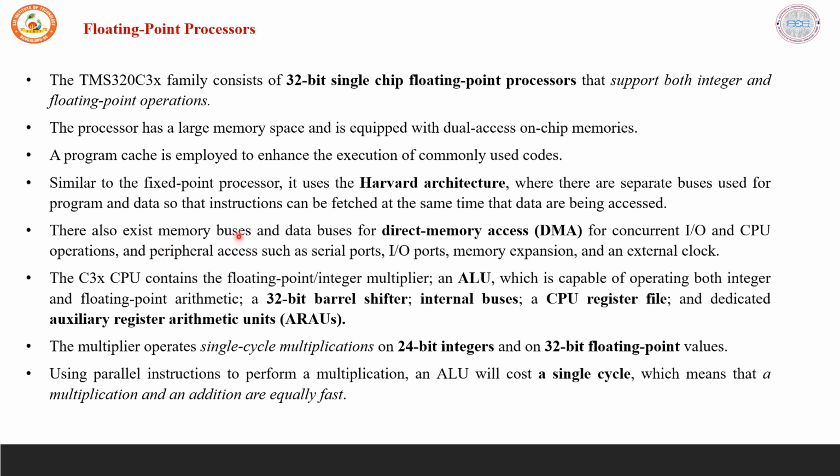There also exist memory buses and data buses for direct memory access, for concurrent I/O and CPU operations, and peripheral access such as serial ports, I/O ports, memory expansion, and an external clock. The DMA feature allows the CPU to carry out its own operation and not be disturbed for the purpose of input-output. There is a dedicated controller called the DMA controller which handles this operation.